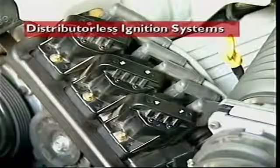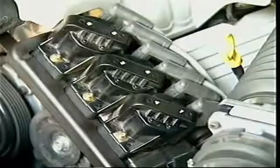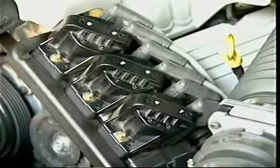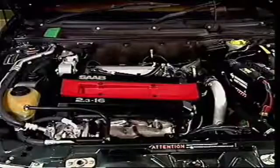In systems of this type, the distributor is eliminated and each spark plug is fired by a high voltage impulse from an ignition coil shared with a companion cylinder, or by an individual coil specifically for that cylinder. This is referred to as direct fire ignition.